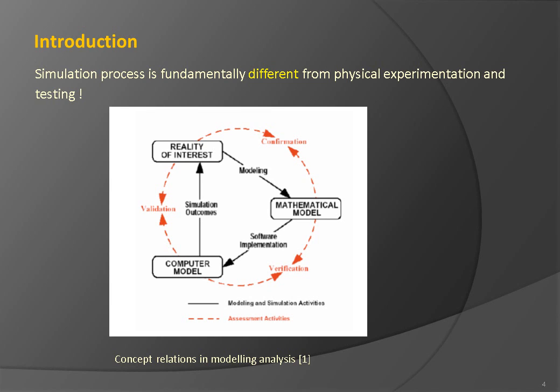Verification activities are required to confirm that the computational implementation accurately represents the mathematical conceptual description. In addition, validation looks at the degree to which the computational model is an accurate representation of the real world from the perspective of the intended use of the model. These assessment activities shall be an integral part of the simulation quality assurance process. More on the subject will be said later.